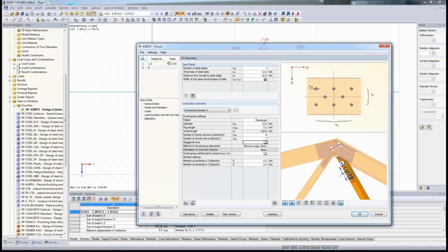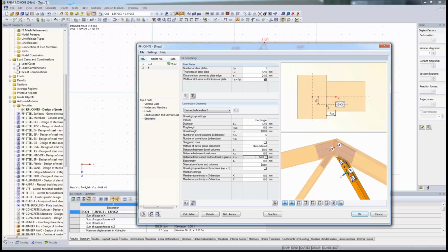And in Z direction, choose 1. And then as a distance, we choose also user defined and 8 centimeters in X, and there's nothing to do with A2, and A3T we leave actually like it's proposed by the program.